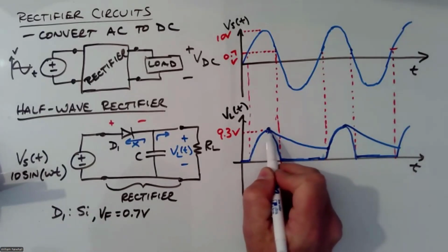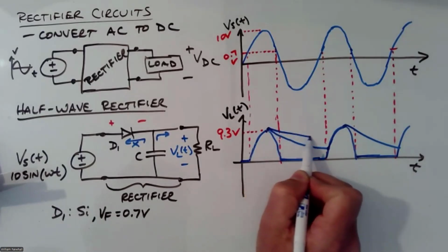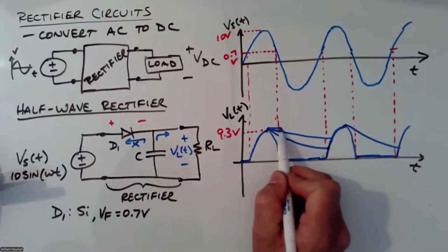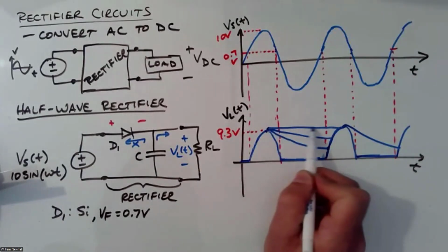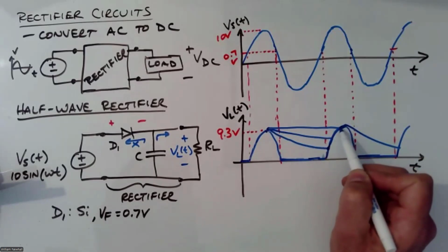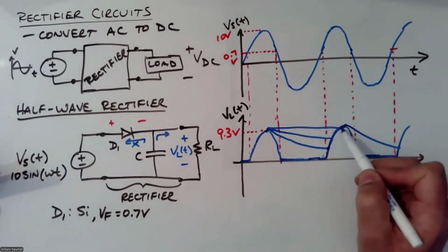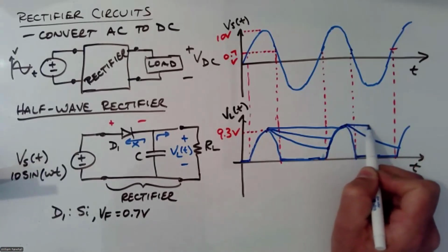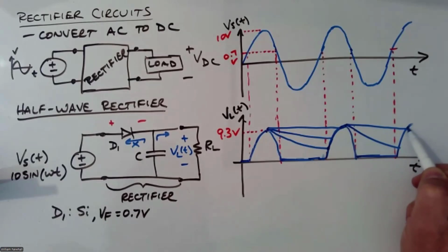And so if I use a bigger capacitor, I might get that, right? And if I use a really big capacitor, I make it something like that, just a little exponential decay there, right? And before it has a chance to decrease significantly, I hit one of these charging half cycles and the whole thing happens again, right?